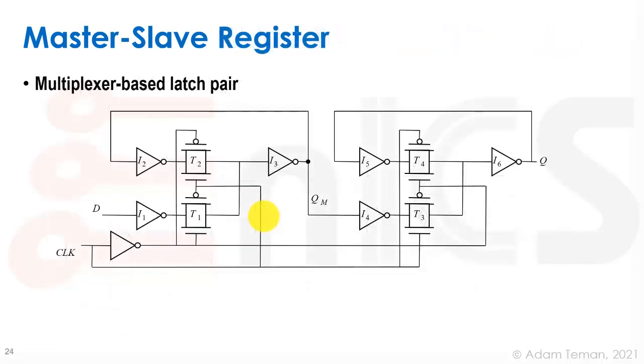So if we go down into a lower level schematic, we can see here that what we'll do is take the clock, and we make a positive, a negative, and a flipped clock in order to control the transmission gates. We have these 4 transmission gates which help our muxes, and our muxes are well buffered in order to make them robust CMOS type gates. And we get our master type of stage and our slave type of stage, and that provides the flip-flop.